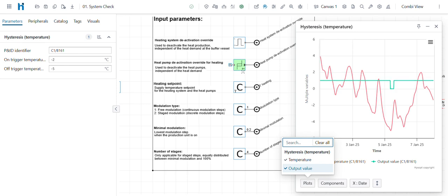Okay, so here a few different things we could do to solve this. Either we could put perhaps a larger buffer tank in order to try and bridge that time at which the installation is at smaller than -5. We could take away the safety. Of course, this is just trying to protect the COP of our heat pump. We could also install a hybrid system where we would have a boiler as a backup if the temperature goes below a certain temperature. All those are valid solutions.